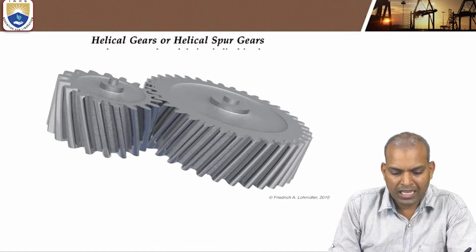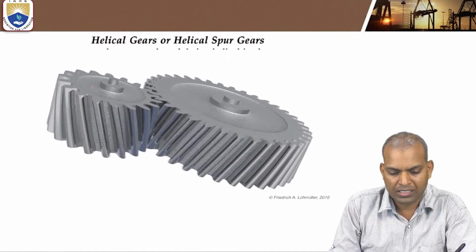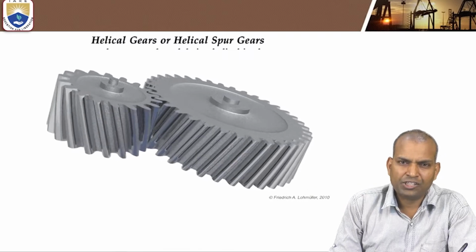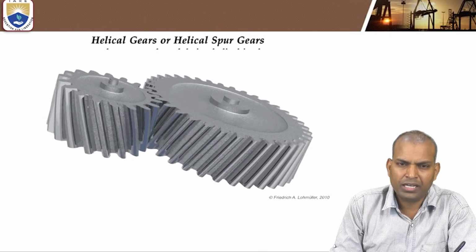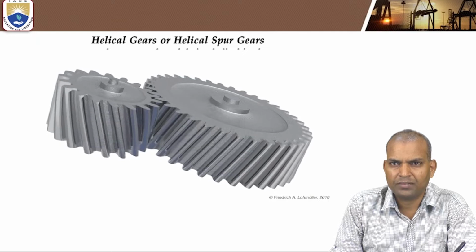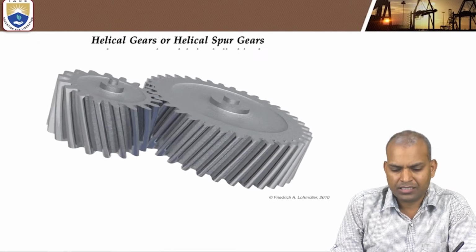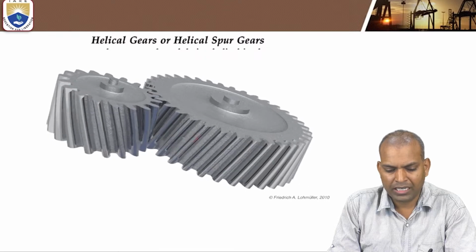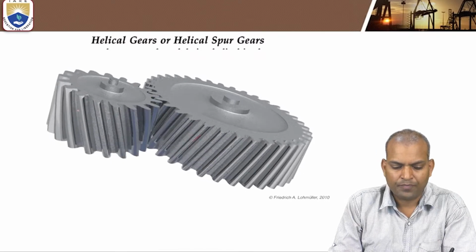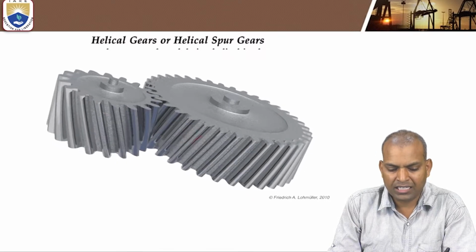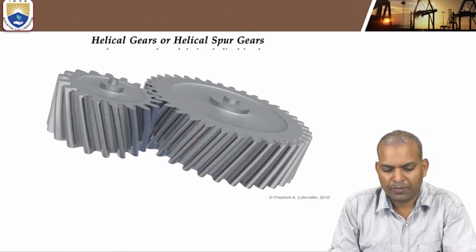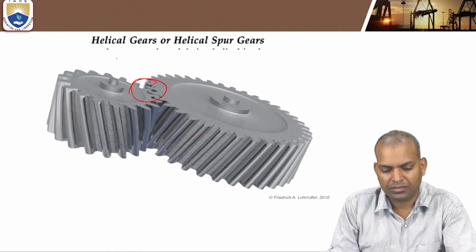So these are the helical gears in motion. You can see how they contact and transmit the motion. The meshing is external mesh, therefore they rotate in opposite directions to each other. The wheel with the larger helix is called the gear and the small one is called the pinion. The wheels mate exactly with each other in opposite directions. The meshing is external meshing.